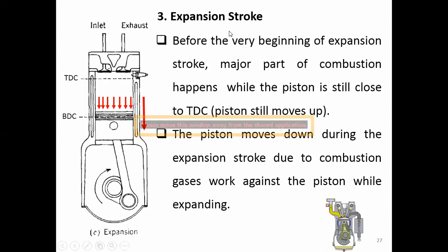Then after combustion happens, the expansion stroke happens. This expansion stroke does not happen immediately, because the major part of the combustion happens when the piston is still close to the top dead center, as I mentioned.